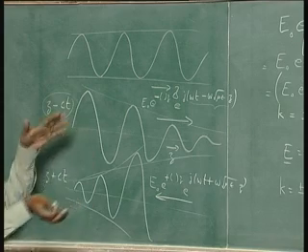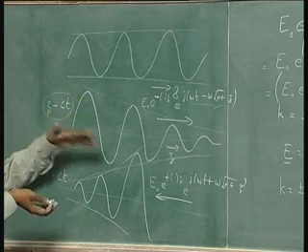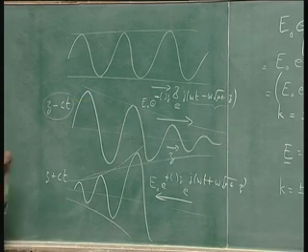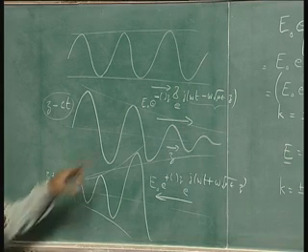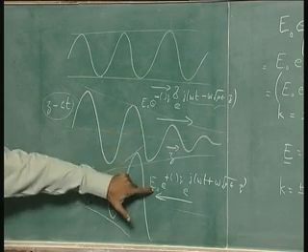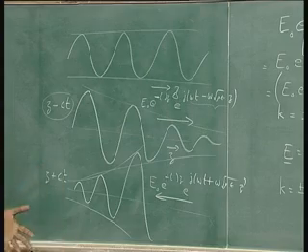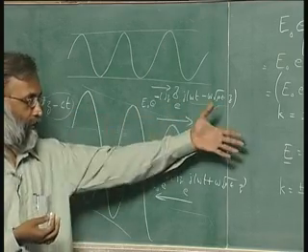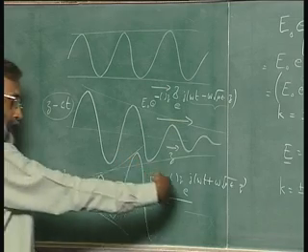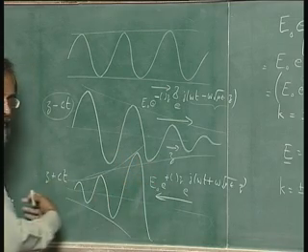So, this growth is a fake growth, it is just out of the mathematics. As far as the physics of the wave is concerned, whichever direction the wave is traveling, in that direction the wave is decaying. It is decaying going into the dielectric in the positive z direction, and if it happens to go in the negative z direction, it is decaying in that direction also.